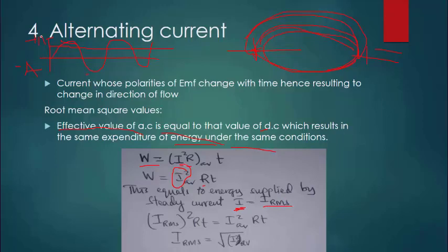Out of these squares, the average is the one that is the effective value, okay? The average current of the variation. So as per our definition, there is a certain value of direct current I which is equal to that current of average. That's why we call it root mean square. The square root of the average of these squares, okay? So we have various squares, square 1 plus square 2. So the square root of that is what we call the root mean square current, I'm sorry.